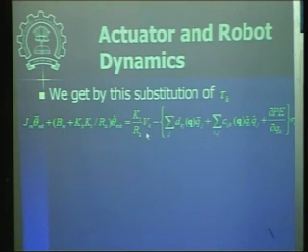This input also remains the same, only in place of tau k, which was a load torque on the motor. Now the motor load is basically because of all these terms in the robot dynamics. So physically you can interpret that this is a load coming because of the dynamics of the robot link.